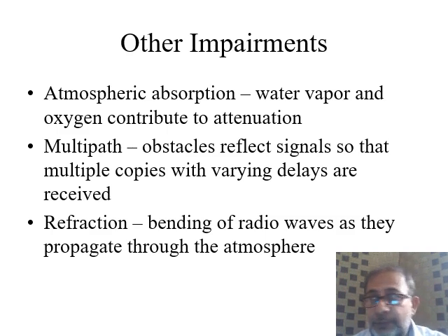Normally in 2G systems that is done, but in 3G systems the rake receiver is used, in which what it does is that it receives the signal copies with different delays and different powers, and it not only gives delay to the earlier coming signals accordingly, so that all are synchronized and they are added up, and a superimposed signal is presented to the receiver.